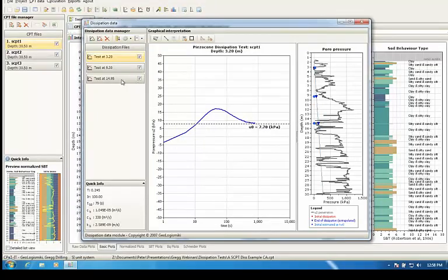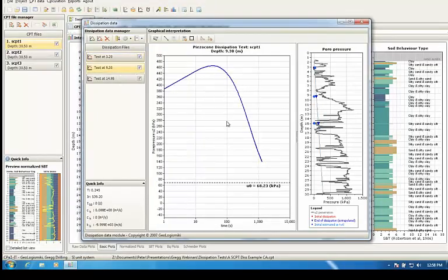And those were all plotted on a log scale. And you'll see that the first one was plotted from -50 to +50, where the others were -50 to 500. I often quite like to plot them all to the same scale. So there is a nice feature in the software that you can just force them all to go to the same scale. So now if I go back to the first one, now you can see it on the same scale. So you can see just a little bit of negative rising up. You see that's actually quite hard to interpret unless you do change the scales. So you can see why I blew the scale up to get a slightly better look at it.